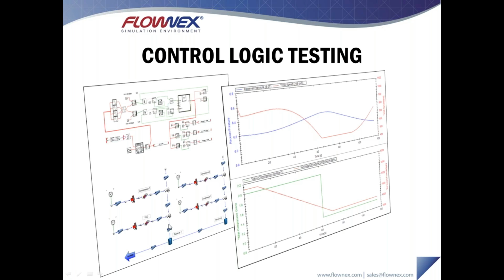As soon as our variable speed drive reaches its minimum value, the digital control section, through all of these logical operations and comparators and switches, delays, counters, many components all integrated together there, this system itself actually turns off one of the baseload compressors. So that's represented by this green line. It changes from 2 compressors online to 1 compressor online. As soon as that happens, we see the pressure in our tank slowly start to decrease over time.